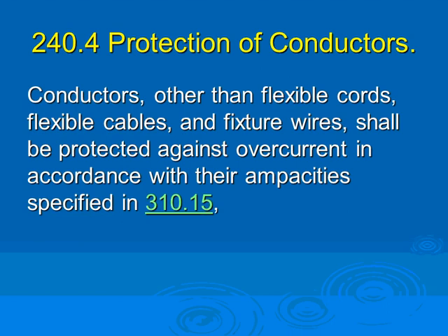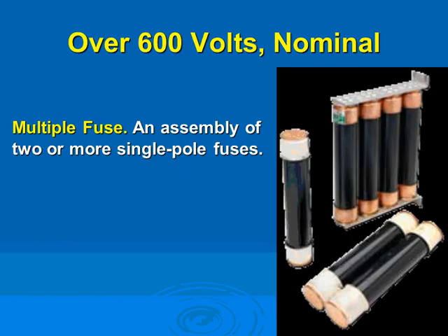Any comments, guys? I don't know about high voltage fuses, but really the major thing in high voltage fuses is what do you do to extinguish the arc when you open these contacts? What's your method of extinguishing the arc? Yes, you have those fuses in parallel. Do they all blow at once? If you have a short circuit condition right in here, and you're paralleling them, would they all blow at once?